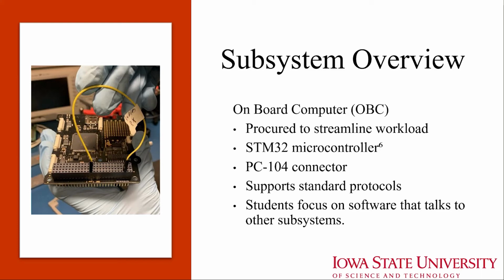In all the cases, we wanted to have a system that used the PC104 connector, and the EnduroSat OBC used that. It also allows us to talk using standard communication protocols. This includes I2C, SPI, and of course RS-232. With that, it also utilizes an STM32 microcontroller as well. And since the students are already familiar with this microcontroller, making the jump from their own built solution to this solution would be a lot easier than jumping to a completely different architecture.